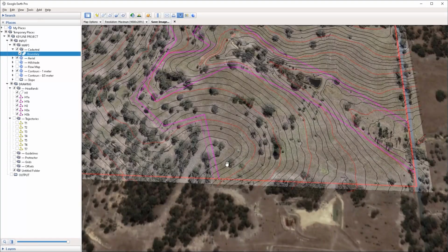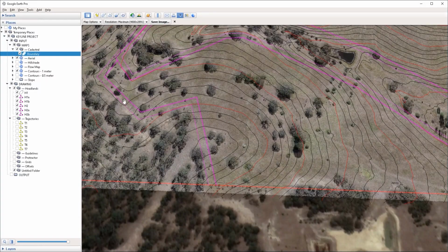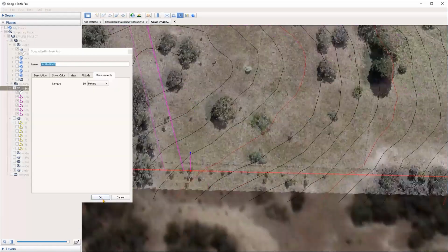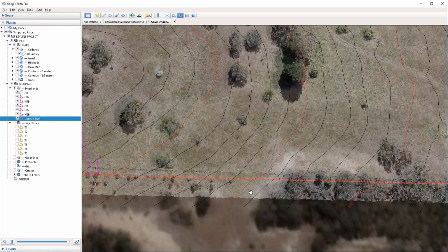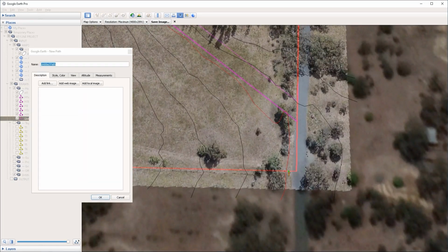Again, I'm going to create a time lapse from this, because it's basically the exact same process as offsetting from any of these headlands. One thing that I would say though is that when you're creating these extensions to use as guides, always try to create a 90-degree extension to the boundary or the line from which you're extending.